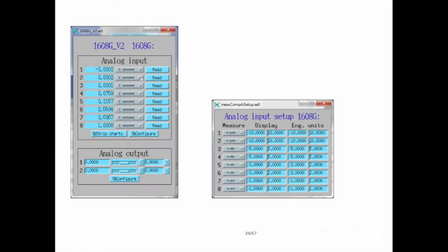Now we've got a substitutions file where we've added these lines for the analog inputs: the record prefix and record name, the port, the address, engineering units, a scan rate, and a precision for each of these analog input records. So that's what the MEDM screen is going to look like. You've got the readback value of that device.